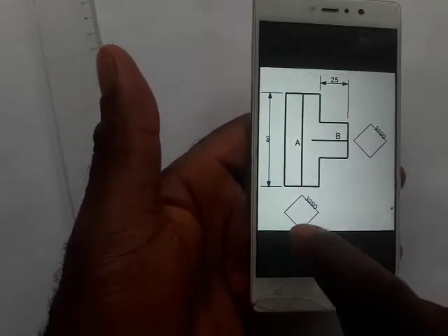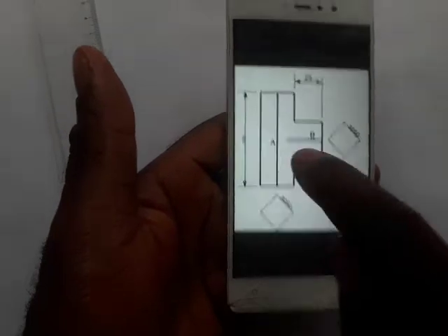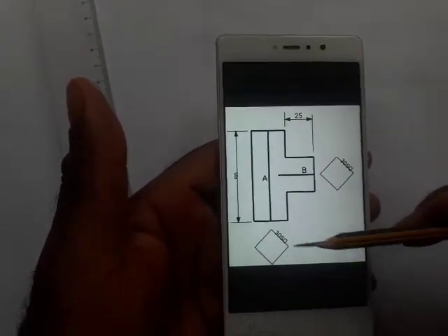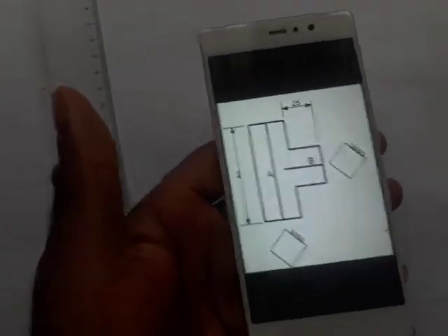What we're going to start with first is the plan. I want to draw the plan because you cannot draw the elevation without the plan. So you start with the plan. When viewed from the top, you see the square shape at the bottom like this. That's what we're about to draw now. So get your 45-degree set square, and watch very closely what I'm going to do.